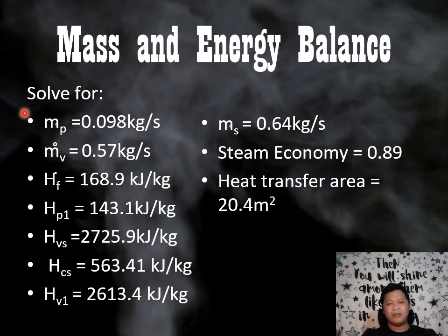Right, so here are the answers to the problem. So you would know kung tama yung nagawa ninyo. Again, you solve it more or less in the order na pinakita ko yung mga things to solve for sa previous slide. And you can use the equations for single effect evaporator in the earlier slides to try and solve them one by one. The key here is to use the steam table. Okay, first to interpolate the steam temperature, then from there makukuha nyo through interpolating again for each one itong value na ito.